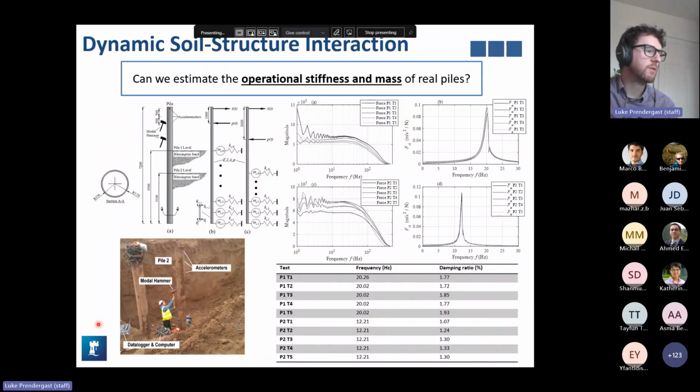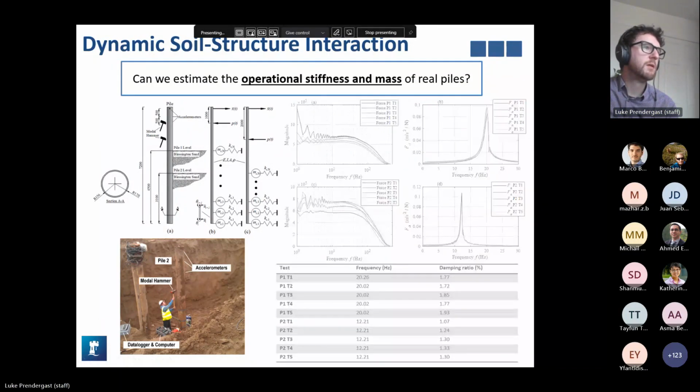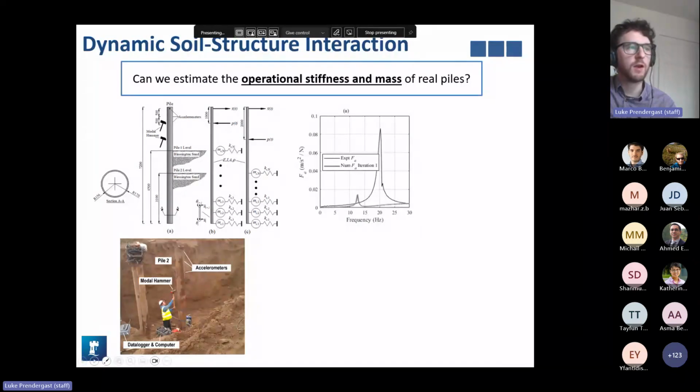So to show you what the results look like, the iterations are as follows. The numerical predictions all converged within 4 iterations, but it is important to note that we had the exact profile that we knew we needed, and we weighted that. In this particular case, we have the output only data, so the frequency response function, and we are predicting the stiffness from the small strains Young's modulus profile, which was measured from multi-channel analysis of surface waves. So that has some error in that respect.